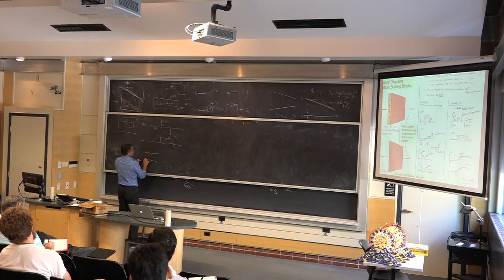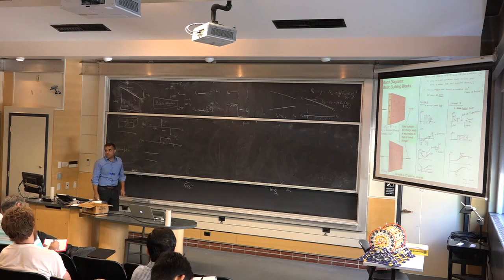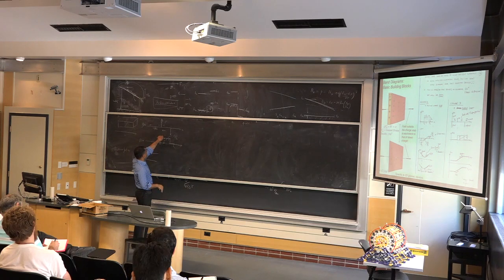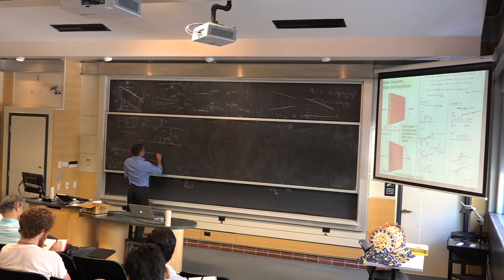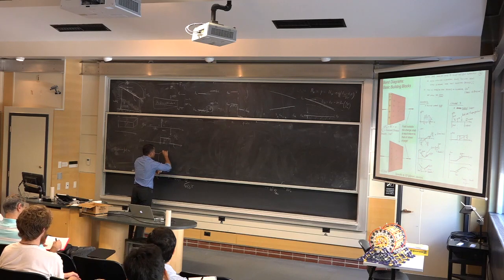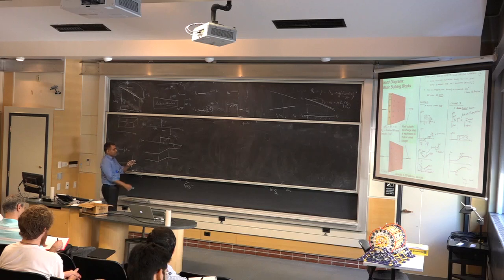The bands remain flat. But the moment you get into that region, there is a large field, so that if I release an electron here, it always wants to go to the left. You see that? Because it wants to go to the positive charge. It's getting, in some sense, hammered twice. It's getting pulled by that. It's getting repelled by that. Okay. So as a result, the band diagram will be, and the field is constant, so the potential changes linearly. So the band diagram will look like that. Okay? The bands will bend. Does that make sense? We're just drawing pictorial representations of the Poisson equation and nothing more than that really.